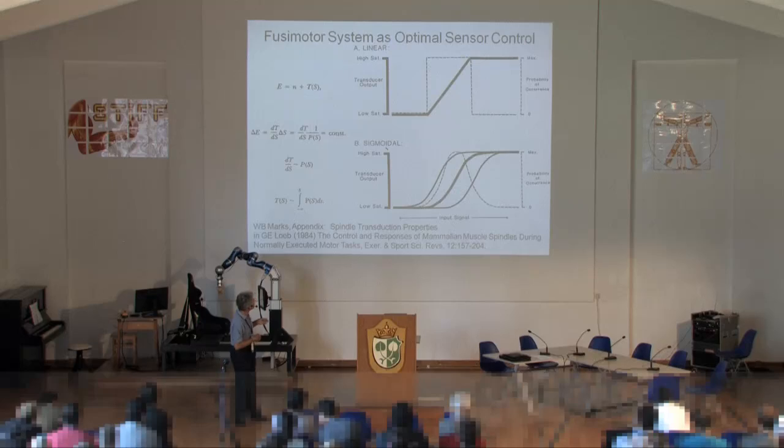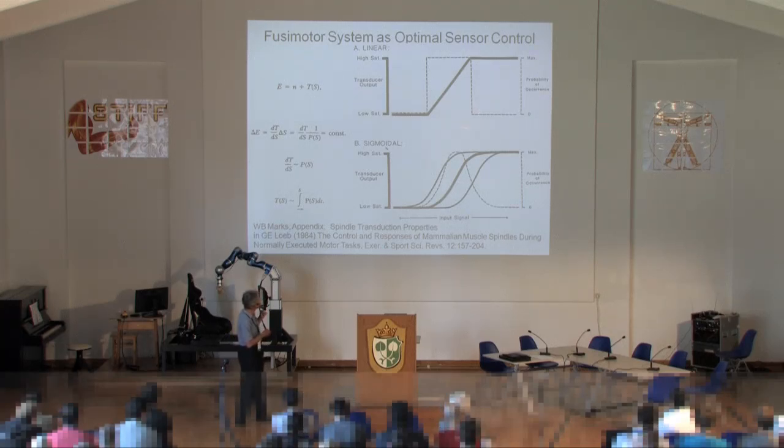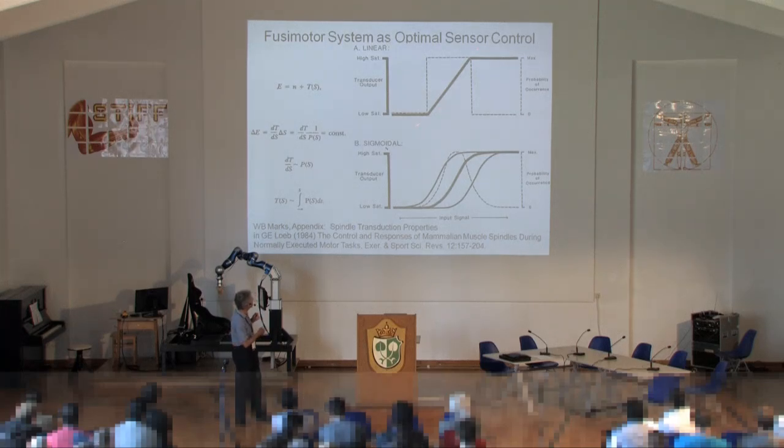In mechanical systems, when you're designing transducers, we know that the transducer will have some low saturation and some high saturation, which is no longer sensitive. And you just assume that over the entire operating range of input signals that you might want to sense, you would be best to have something that's linear over its available output range, and then just hope that its noise is low enough that you can get whatever resolution you need over that range of operation.